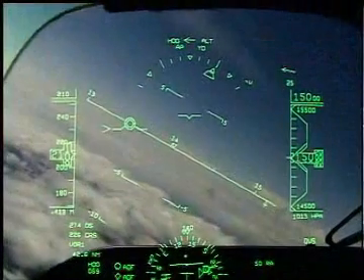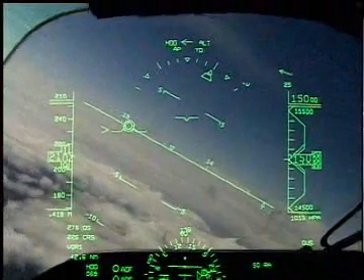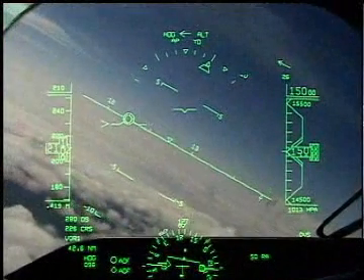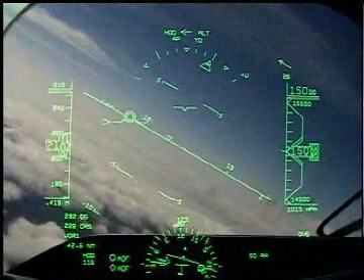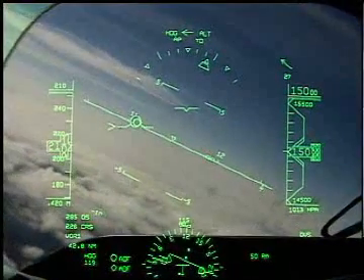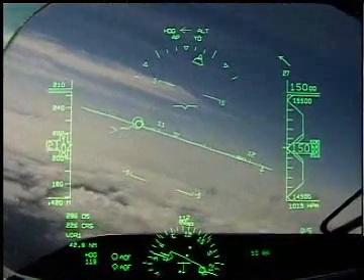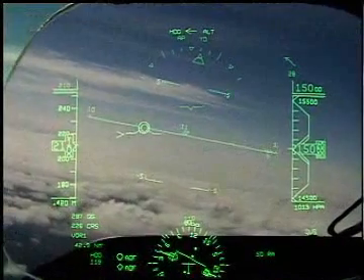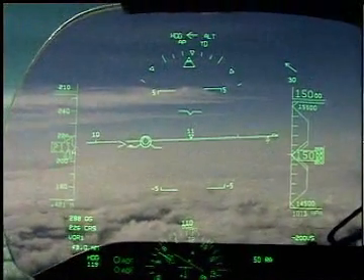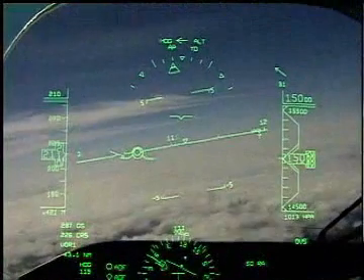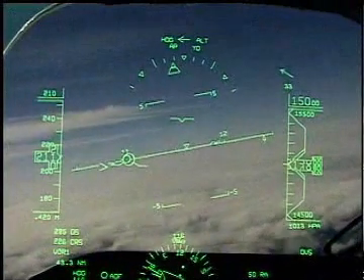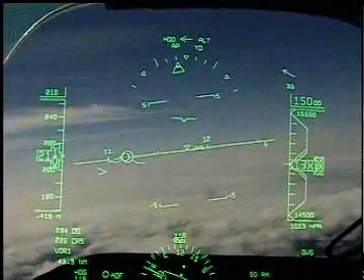In a level turn, the pilot needs only to maintain the flight path symbol centered on the horizon to maintain altitude. In a level 30-degree turn, the angled portion of the flight path symbol will overlay the horizon line. The target altitude is also maintained by holding the selected altitude pointer inside the altitude scale index. Observe the autopilot setting as well as the assigned altitude, the current heading, and the airspeed indication.